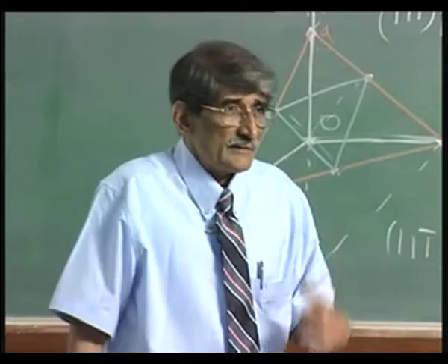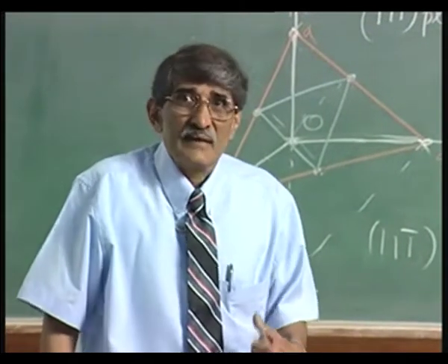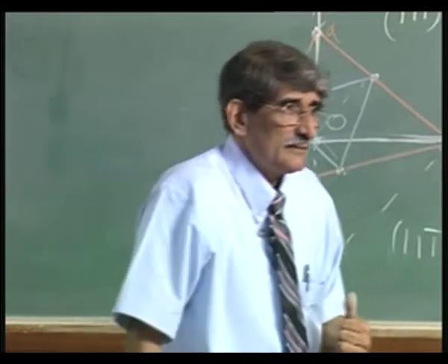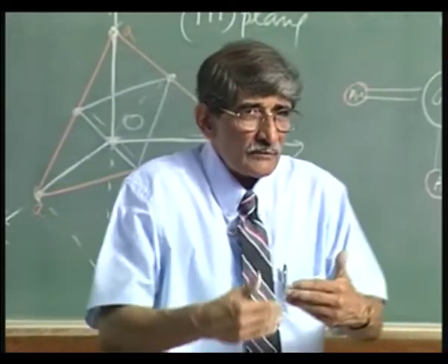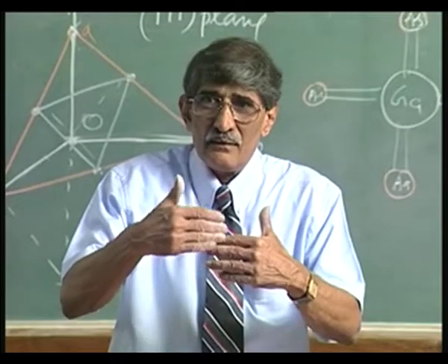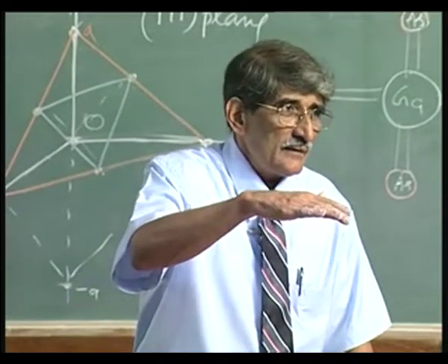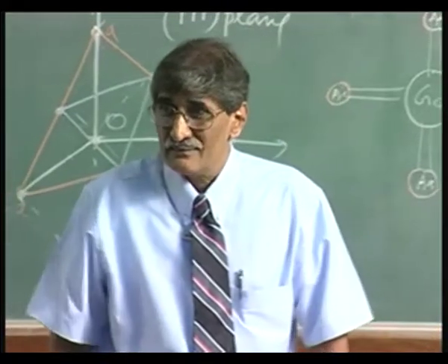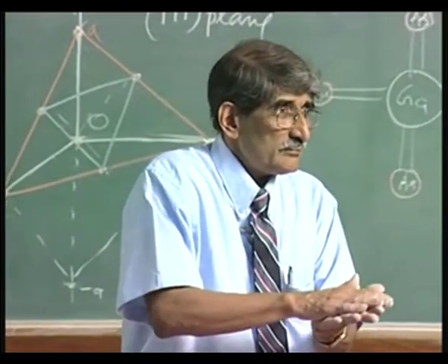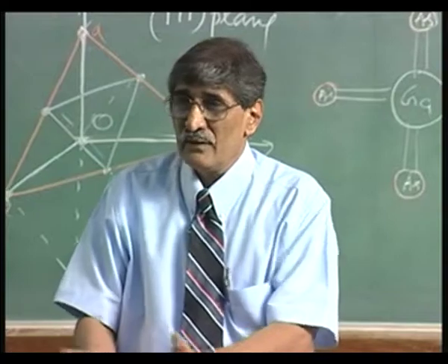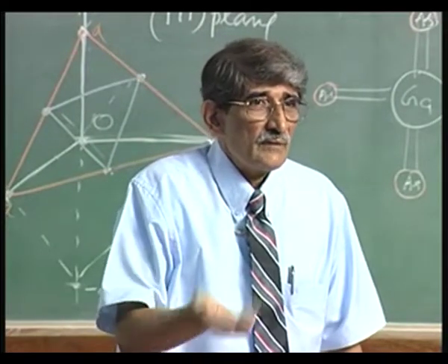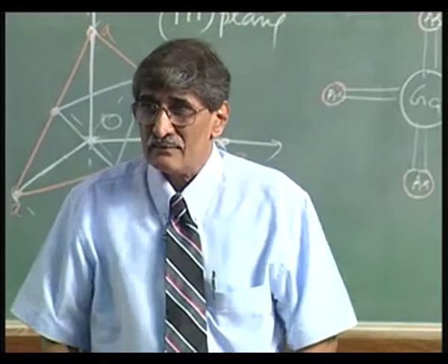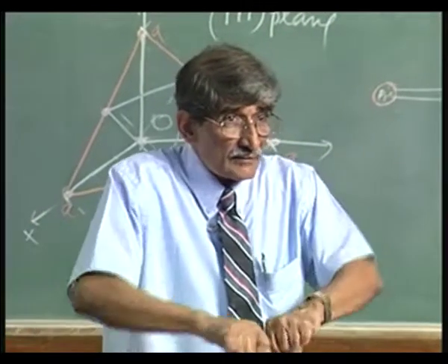If you take gallium arsenide, the cleavage plane, can you take a guess? If you take the 100 plane, you have gallium, arsenic, gallium, arsenic. That means there is a force of attraction between the two, in addition to the usual bond. If you take 111, it is gallium, arsenic, gallium, arsenic. Again, that electrostatic force of attraction is there. It becomes difficult to tear.